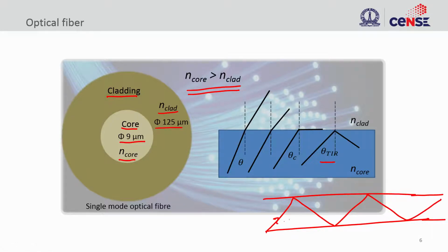So, this is the reason why you can make optical fibers kilometers long, yet without any appreciable loss. We are talking about 0.02, 0.01 dB per kilometer, right, very small loss. So, all the energy is confined inside.